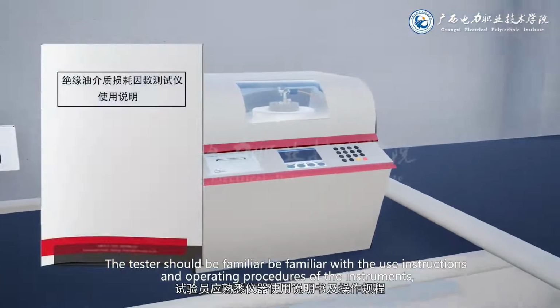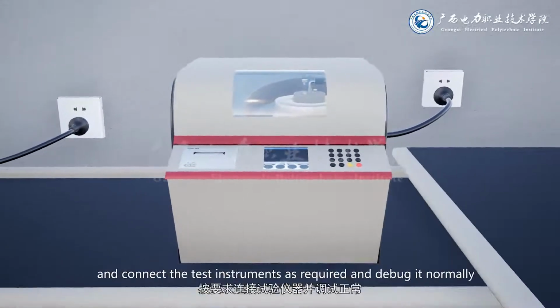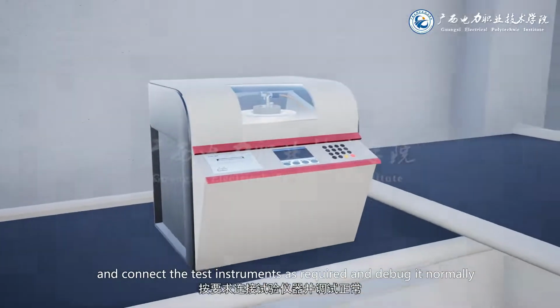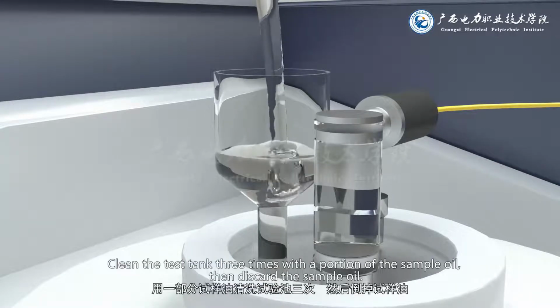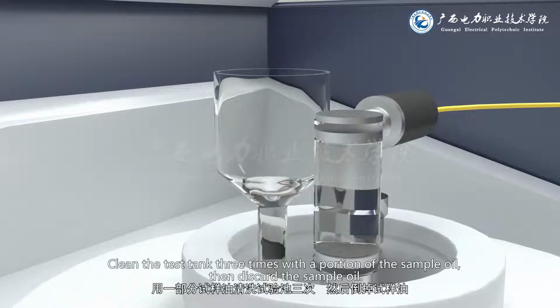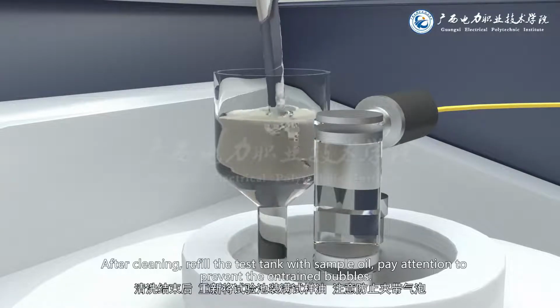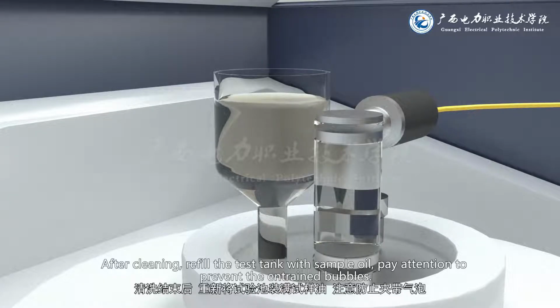The tester should be familiar with the use instructions and operating procedures of the instruments, and connect the test instruments as required and debug them normally. Clean the test tank 3 times with a portion of the sample oil, then discard the sample oil. After cleaning, refill the test tank with sample oil. Pay attention to prevent entrained bubbles.